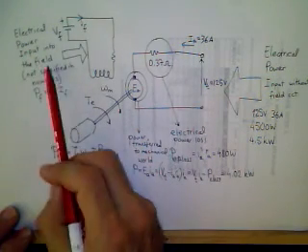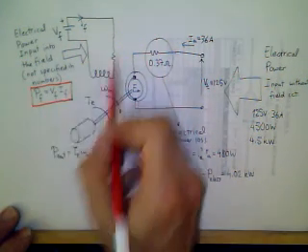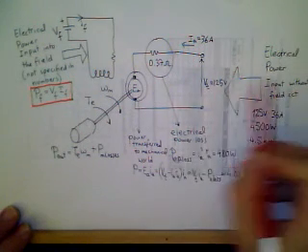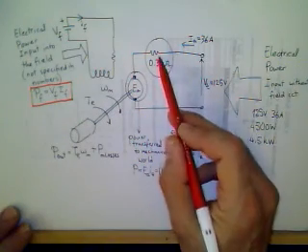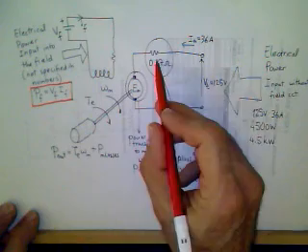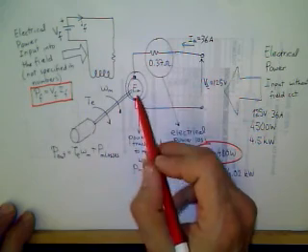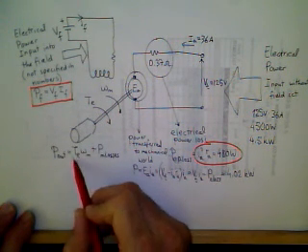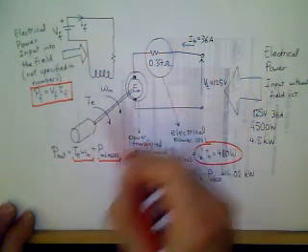We give some electrical power into the field of this motor. That power is field voltage times field current, but it's not specified in the problem. The main electrical power is given through the armature terminals or main terminals of the motor. Some power is lost in the armature resistance. This power is calculated to be 480 watts because we know the armature current and this resistance, and power is transferred at this point across the armature to the mechanical power. So gross mechanical power is net mechanical power output plus losses. So there is a power transfer from the electrical side to the mechanical side along this axis.